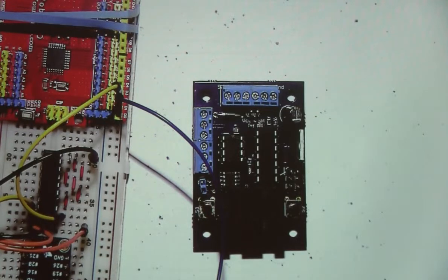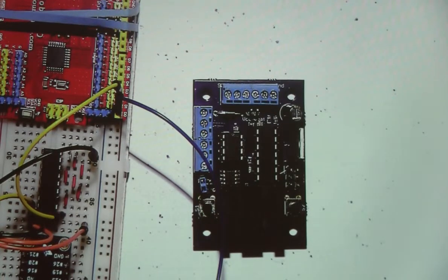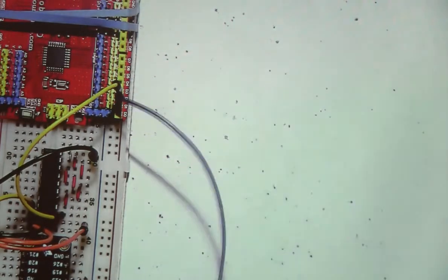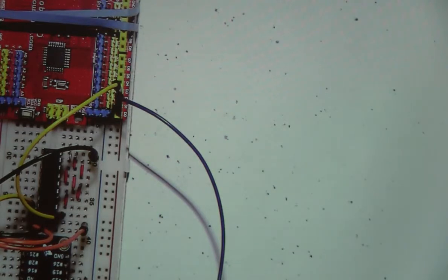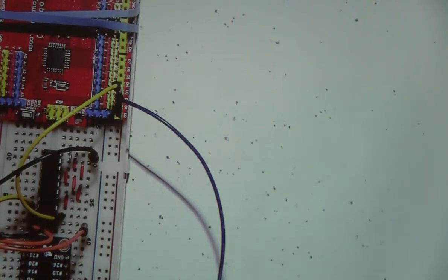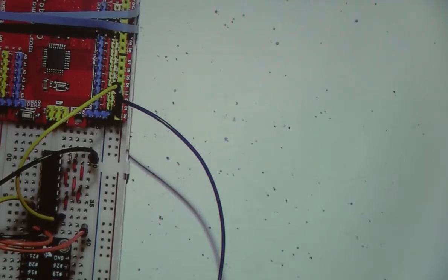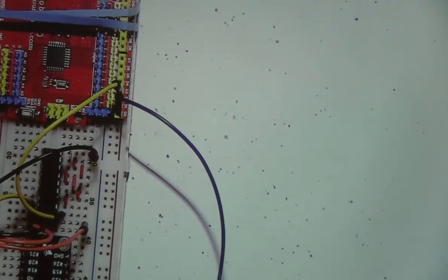So this has an ATtiny84, which you program with the Arduino IDE, and it has a 485 physical transceiver, which is supposed to be able to go up to 4,000 feet over telephone Cat3 cable. It has telephone jacks, and I just daisy chain however many of these I want. And then there's a little shield, not called a shield, what do they call it, a Raspberry Pi hat?